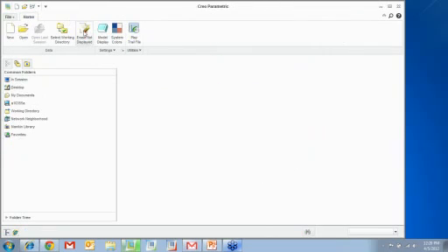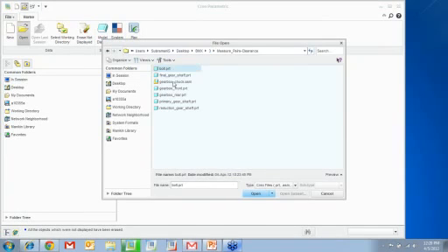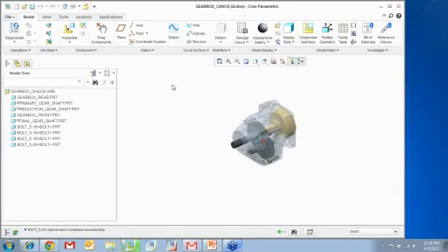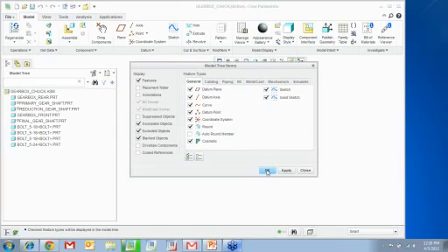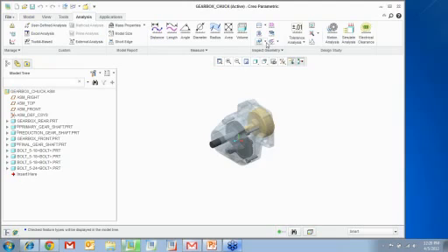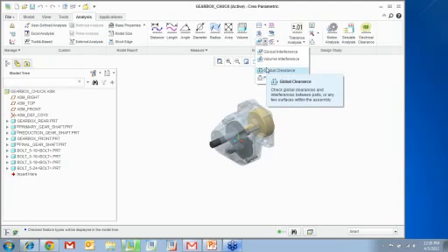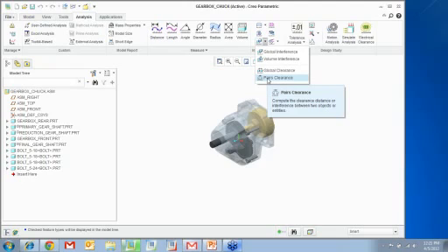All right. So next thing we're going to talk about is clearance. So let's look at a pairs clearance example. So I want to know what is the clearance between two parts or two surfaces. So I'm going to go ahead, get the features shown up in the model tree. Go to analysis, and right here you have global interference, volume interference, which tells you if there is anything else interfering with the closed quilt. You have global clearance, where you can check clearances or interferences between parts or any two surfaces in an assembly, or you can do pairs. You just pick a pair of parts and see what's wrong with that.